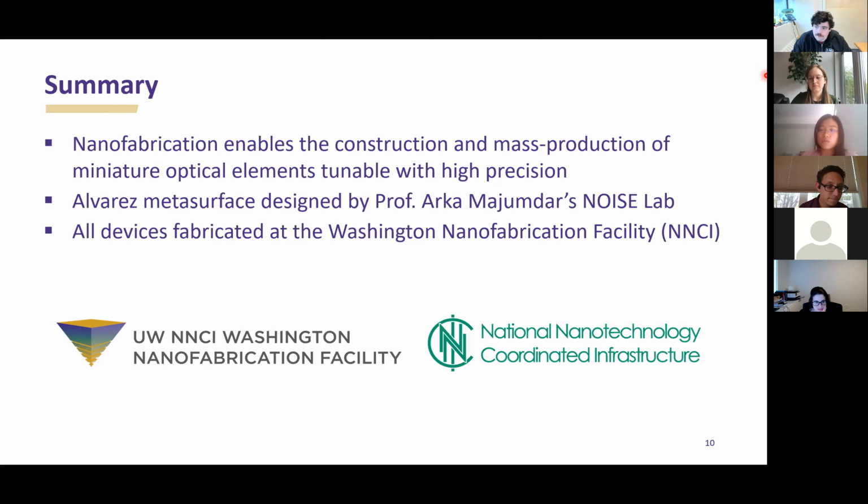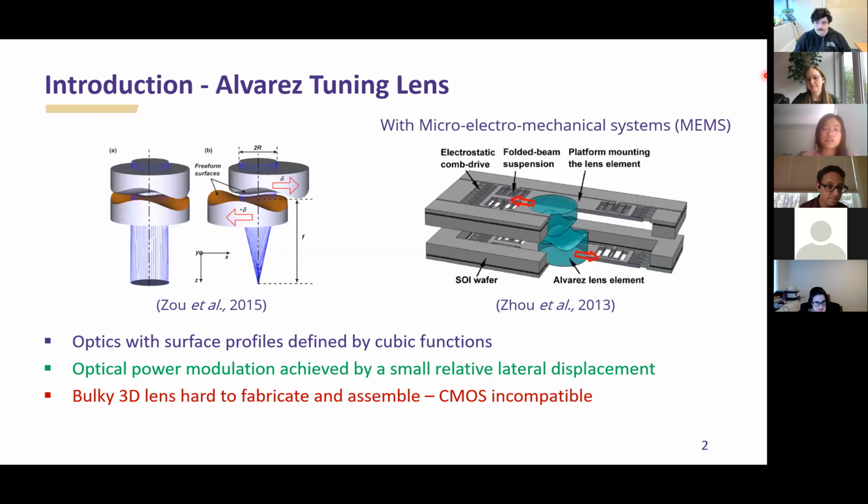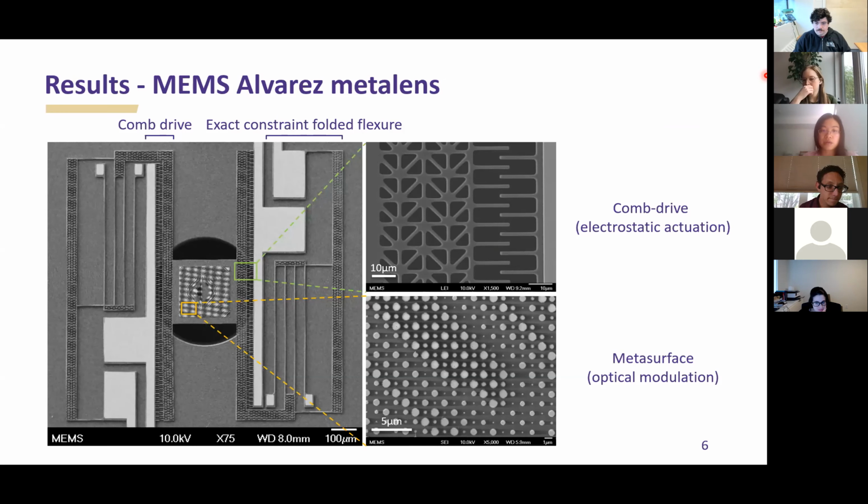So the thing is, with the Alvarez principle, the mechanism we're using, there's actually no limit on how far it can go. In this case, it all depends on how well you can design the main structure. For example, in this device, which is the first round of the experiment, we designed the moving range between the fingers to be 10 micron. To safely control the device, we can only move up to 7 micron here. But we are doing further devices as well.